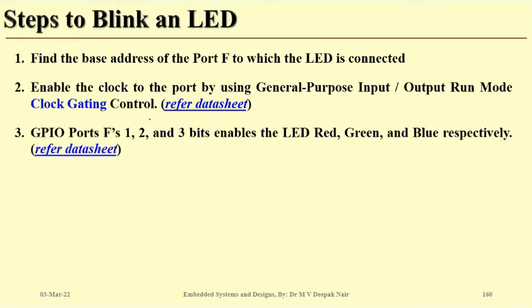Now, since we were using port F, because there are three LEDs built into the board itself, the red, green and blue LEDs, we also saw in the data sheet which pins are connected to these three LEDs.